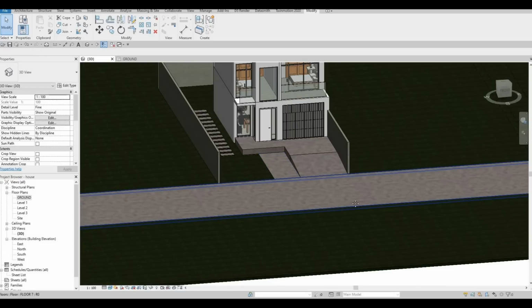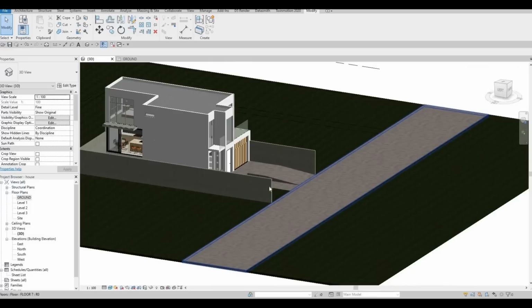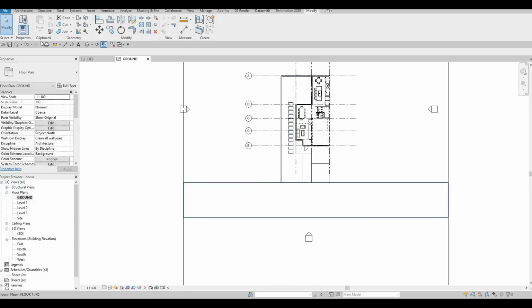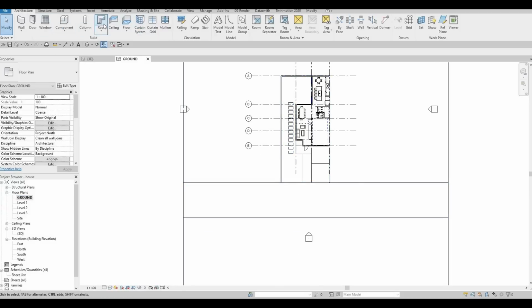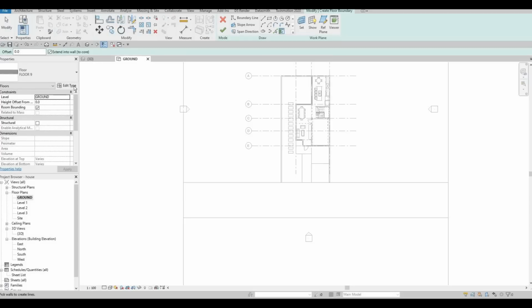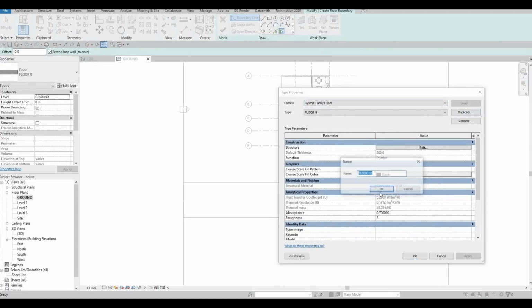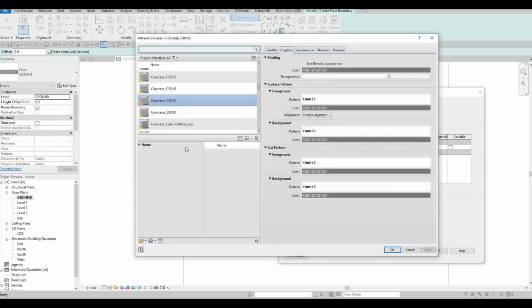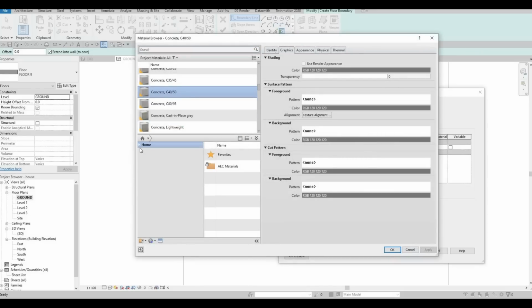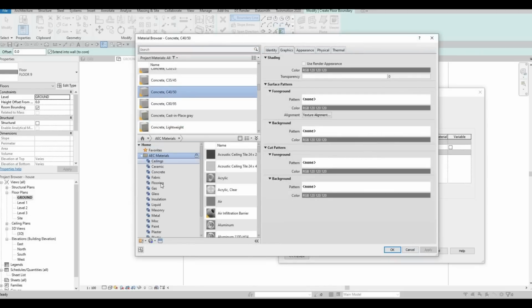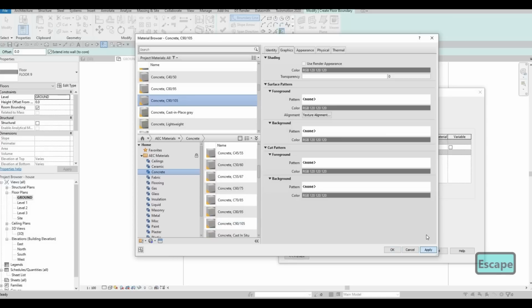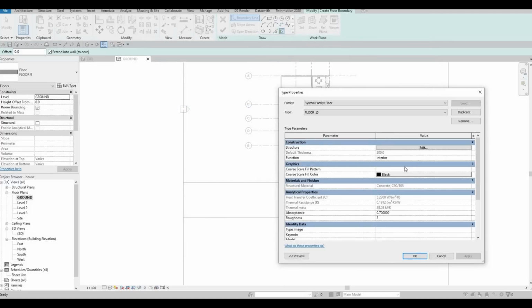And then we're going to add in the side street or the sidewalk. What I'm going to do is add in another floor: edit, duplicate, floor number 10, and then this will be another concrete material. Pull it up, click apply, OK, and then OK.